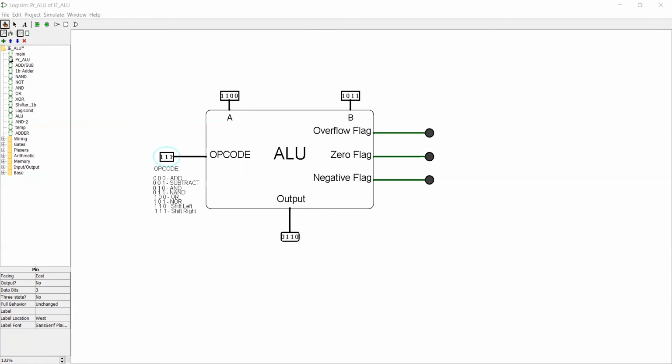In conclusion, I have talked about my problem statement, to reduce the area occupied by the transistors. My implementation was using the transistors. I mimicked the operation of my various gates and used those gates. My novel features were the inclusion of the adder-subtractor combo and the inclusion of a logical shifter.